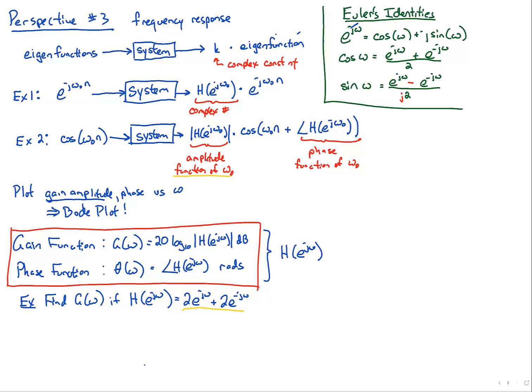You just did that in your head, but it looks just like those Euler identities. It always gets confusing to me if it's 1 cosine of omega or 4 cosine of omega. And what I literally do is I force that 1/2 out of there. And then to make it the same, I'd have to say it's 4 e to the j omega plus 4 e to the minus j omega.